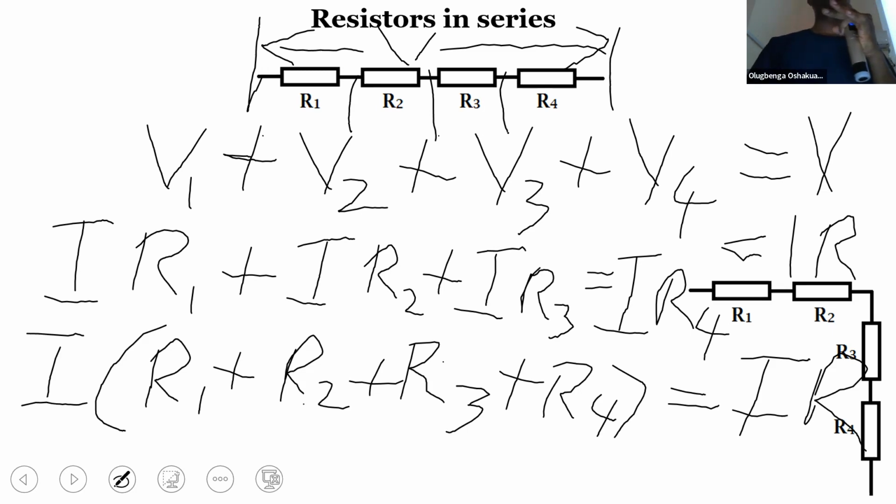All that is available is 100 ohms. Then you can buy two of such and connect them in series. When you connect them in series, you should have 200 ohms that will replace that single one you intended, perfectly.